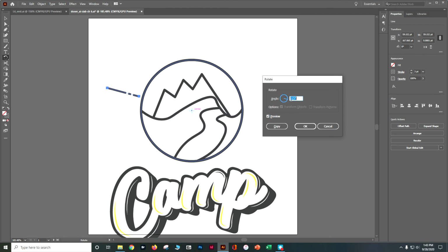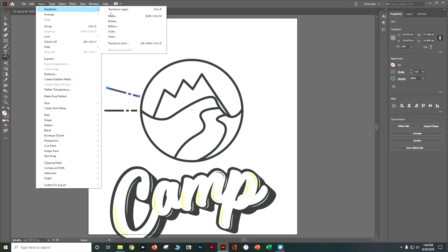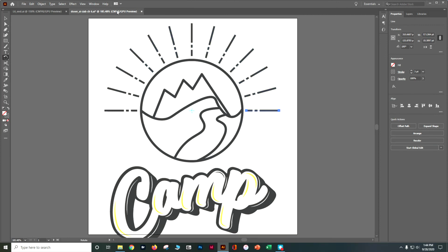So we've got 15 degrees, we've got -15, and we want to say copy. It's going to go ahead and make another one. So we want to repeat that over and over again. Let's go Object and Transform Again. And if you do Control D, you're going to see it'll let you continue to move that around the logo. So instead of having to copy and paste and repeat, this makes it pretty easy.